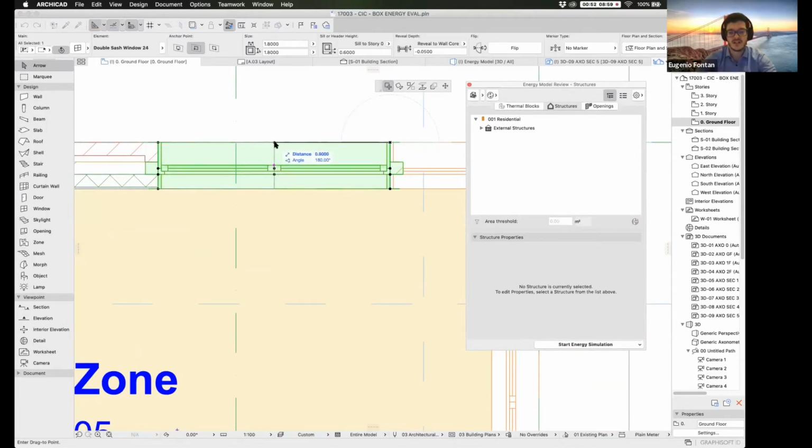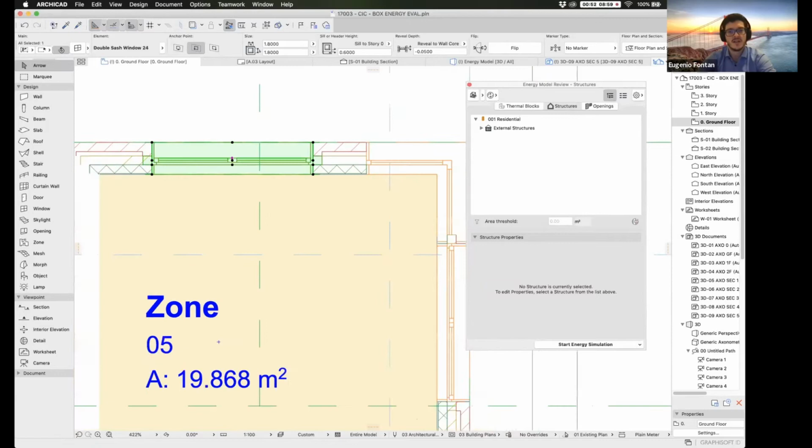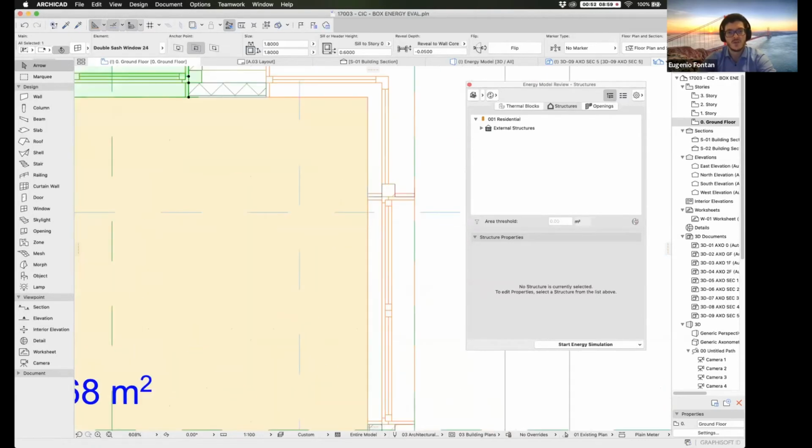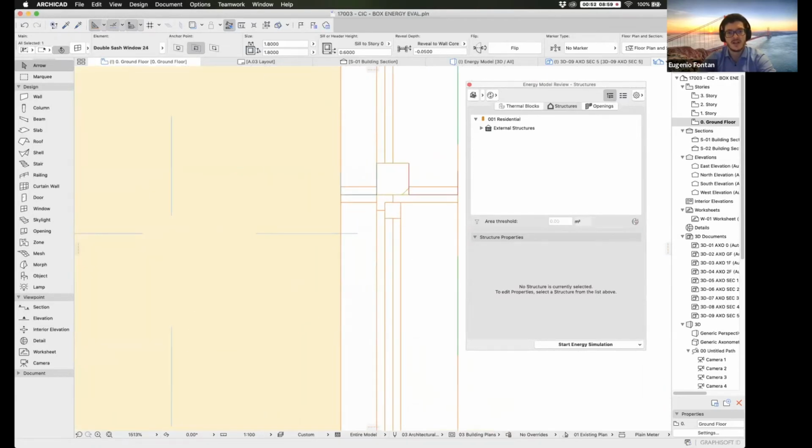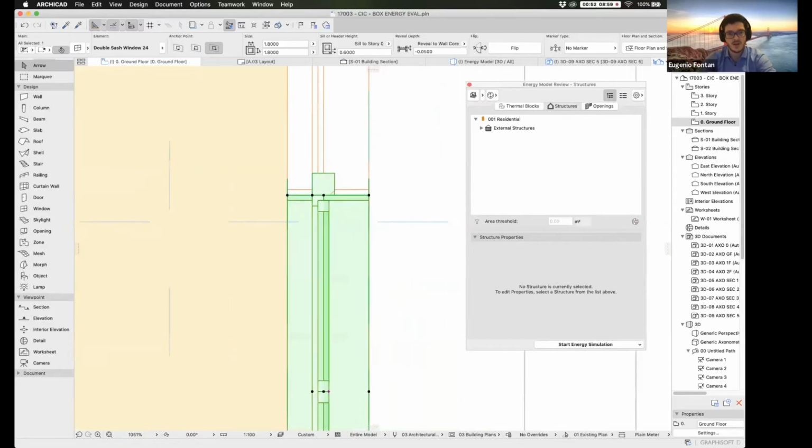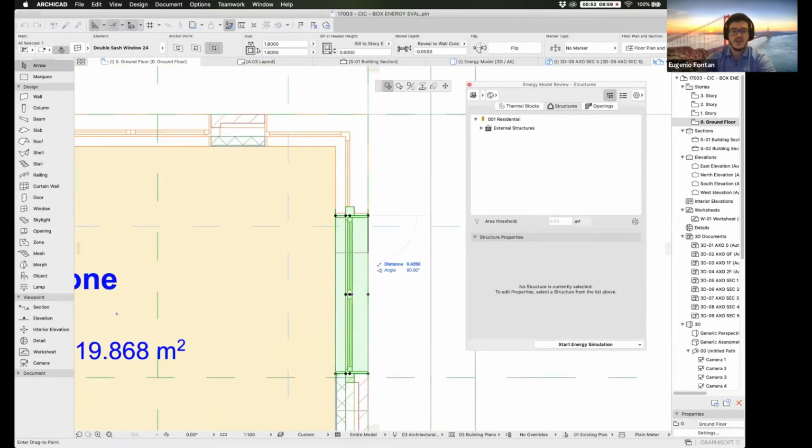I'm going to move it like 0.6, which is 600 millimeters. We just need to input the numbers with the computer keyboard. I'm going to select this window here, one click on this black dot. Because the drag option is already selected on this little palette, I'm going to drag it towards this direction. And I'm going to say 1.5.